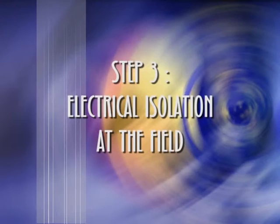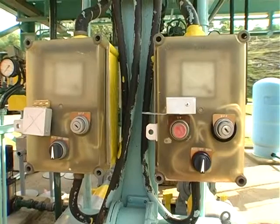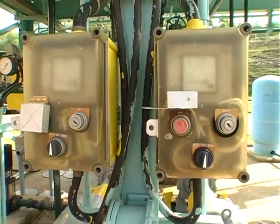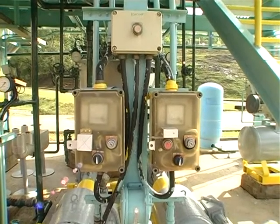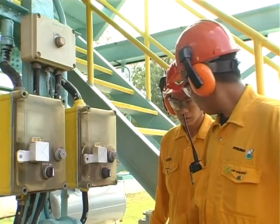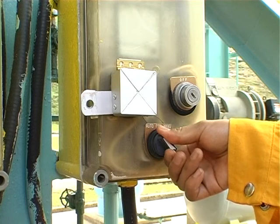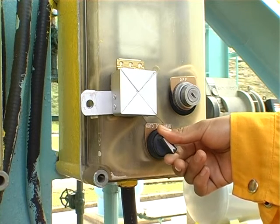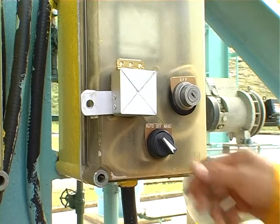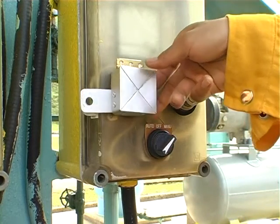Step 3. Electrical isolation at the field. Before testing the field on-off switch, the area around the equipment must be cleared to ensure no one is working within the area. After electrical isolation at the substation, the AAR must check and verify the correct field start-stop switch of the equipment under maintenance.